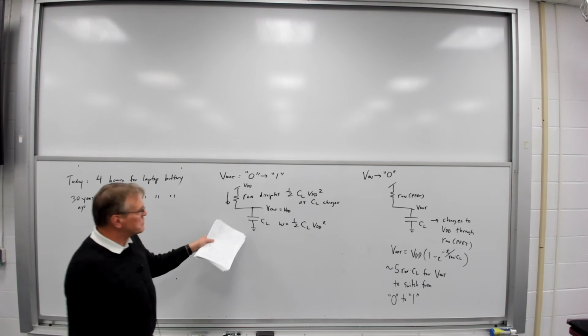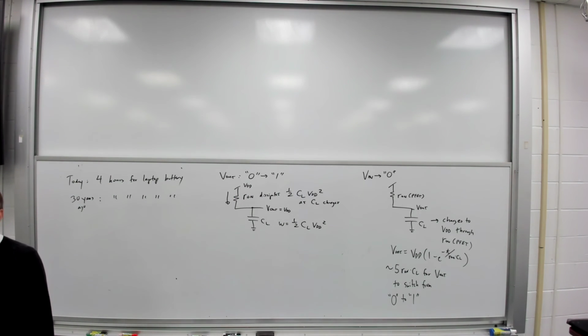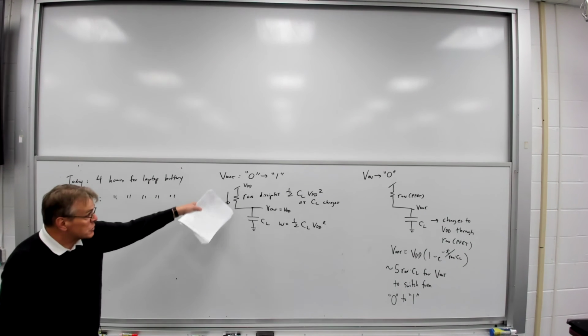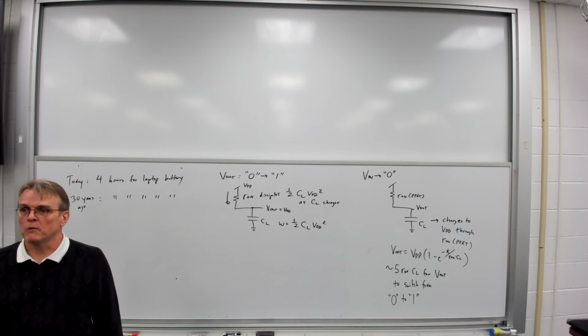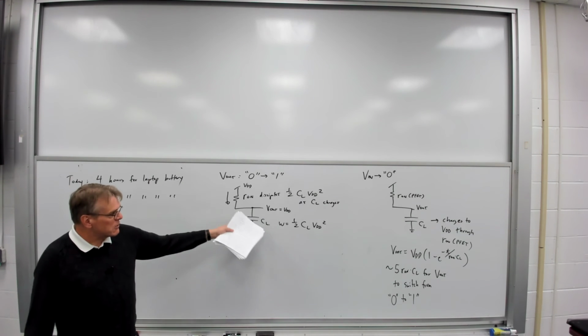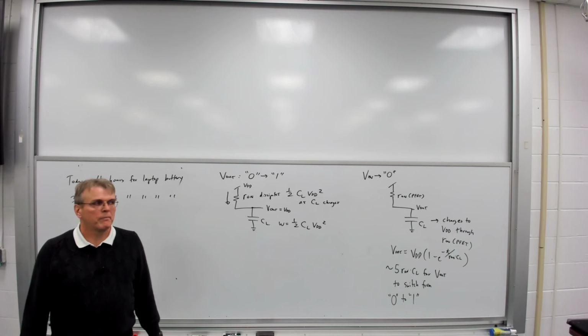So it turns out that charging that capacitor is 50% efficient. And incidentally, this is true regardless of the value of R on. It doesn't matter if it's large or small. You'll always dissipate as much energy as you actually store in the capacitor.